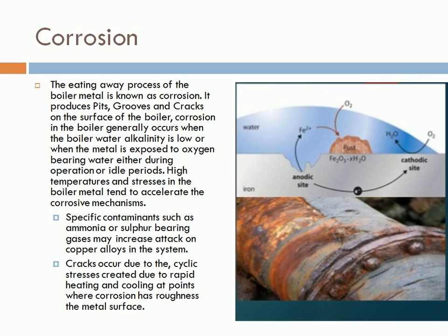Additionally, feed water is typically alkalized to a pH of 9.0 or higher, to reduce oxidation and to support the formation of a stable layer of magnetite on the water side surface of the boiler, protecting the material underneath from further corrosive effect. This is usually done by dosing alkaline agents into the feed water such as sodium hydroxide, or we can say caustic soda, or ammonia, right?